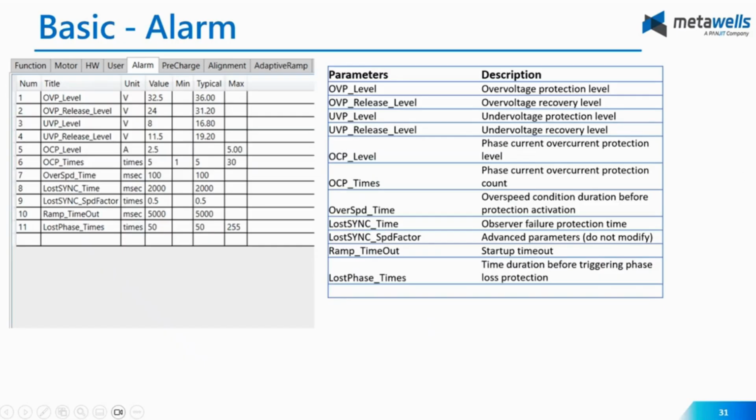Okay, so this is a protection window. There are some parameters you have to input. The previous page introduced some protection functions. On the basic protection page, you can input specific parameters like over voltage or over current level, over current times, and over speed time, etc.